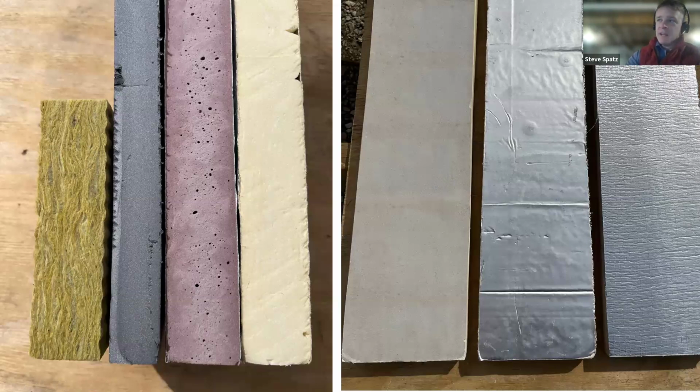But what I'm hopefully getting at for you all to dig into is to just be curious about what those options are. There's so many options out there now. Just being curious about what the different dynamics of each component of that material are capable of doing and how that interacts with the other materials you're putting together into an assembly. So the fiberglass facing on this has a different impact on the drying potential and moisture transport of that insulation versus this foil-faced polyiso, the typical foil-faced polyiso that you see here, and then this, which is a perforated aluminum facing on the foam board as well.